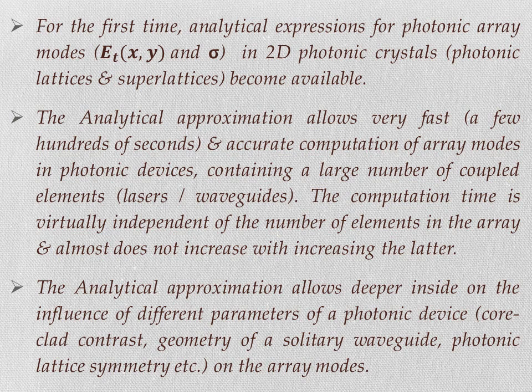The computation time is virtually independent on the number of elements in the array and almost does not increase with increasing the latter. The analytical approximation allows deeper insight on the influence of different parameters of a photonic device, such as core-clad contrast, geometry of a solitary waveguide, photonic lattice symmetry, and so on, on the array modes.